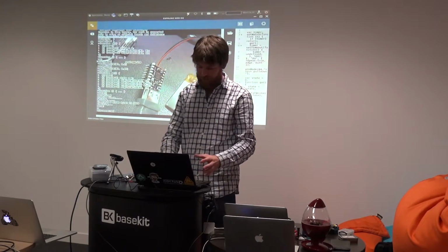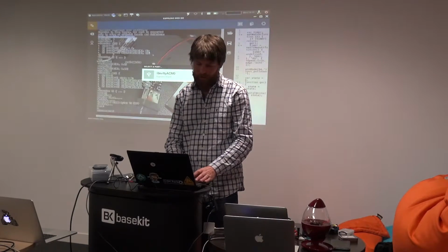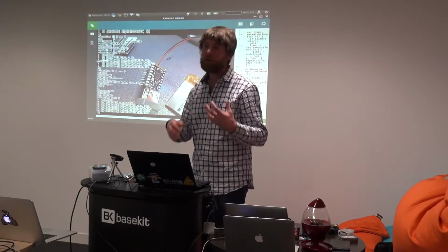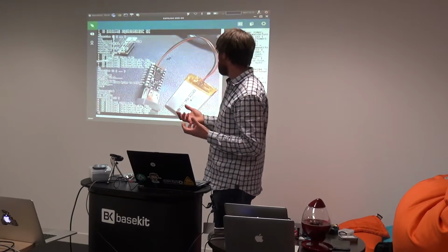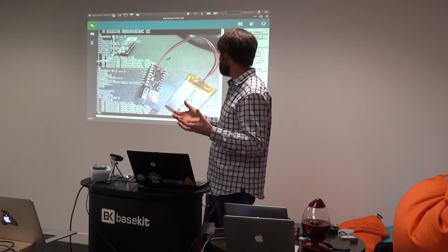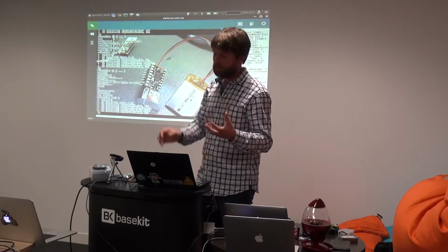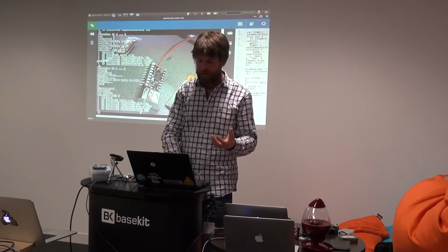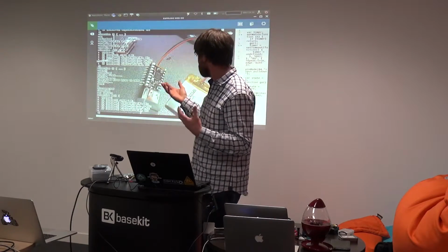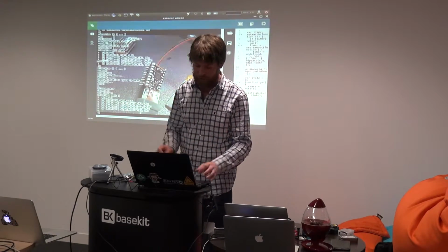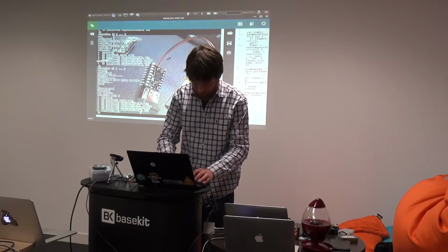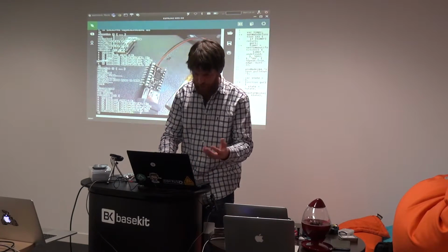we can do one last thing that will make it really, really power efficient, which is to enable something called deep sleep. And you can't enable that normally if you're using analog write, because analog write uses the high-speed oscillator of the chip. So if that turns off when the chip doesn't think it's doing much, then it won't stay kind of half lit. It'll either be on or off. So we'll just do set deep sleep only when the state is naught, so only when the light's off.